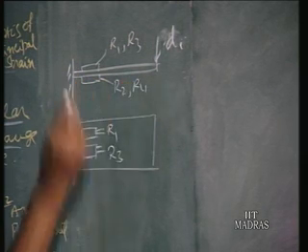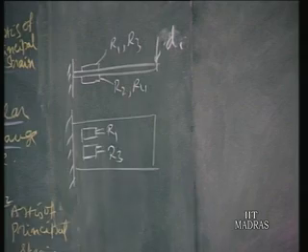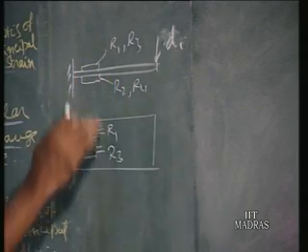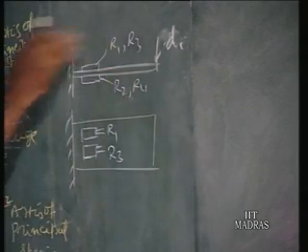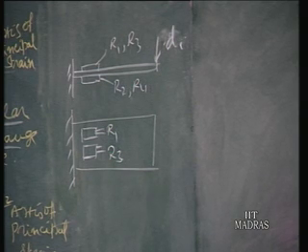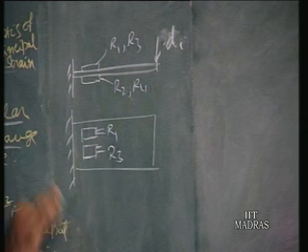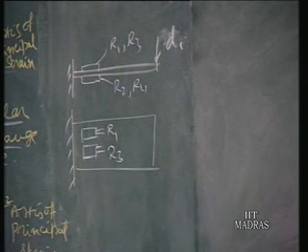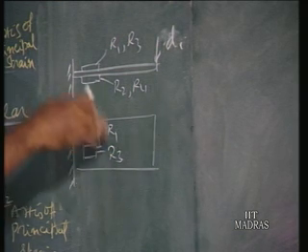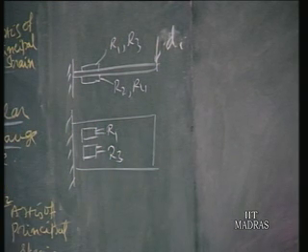And we place the other two, R2 and R4, at the bottom of the cantilever. So that means all the four are active, two in one direction, other two in opposite directions. In such a case, you find the temperature compensation is automatically there. Since all the four arms will be affected in a similar way by temperature, it gets cancelled out. Whereas signal is opposite, so you will get output proportional to the signal. So that is the temperature compensation for different usage of the strain gauges, either quarter bridge or half bridge or full bridge. You have to adopt this temperature compensation.